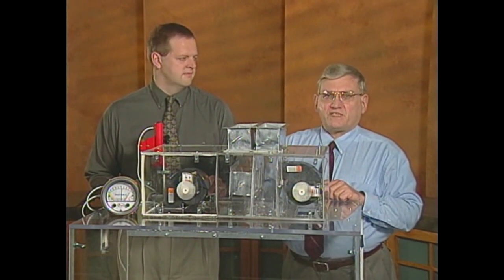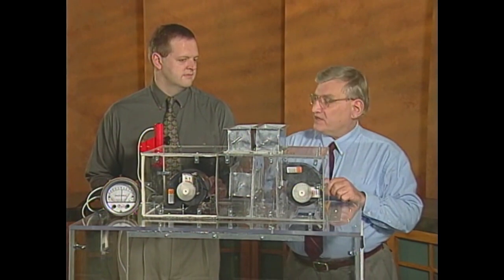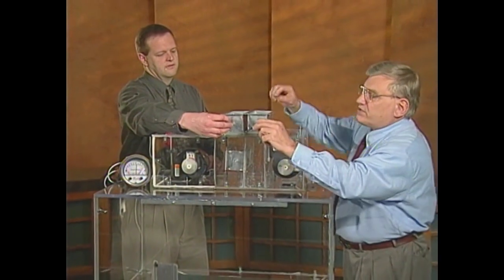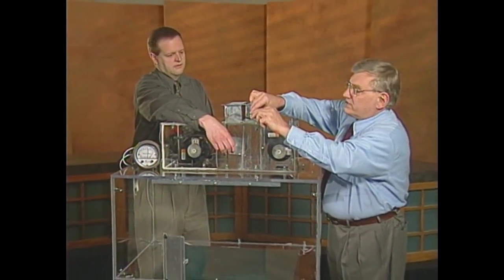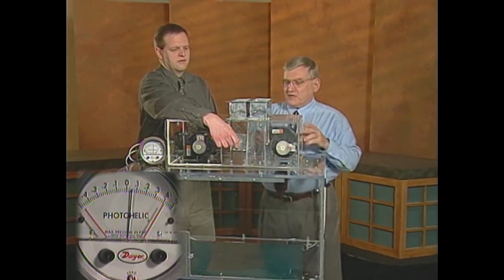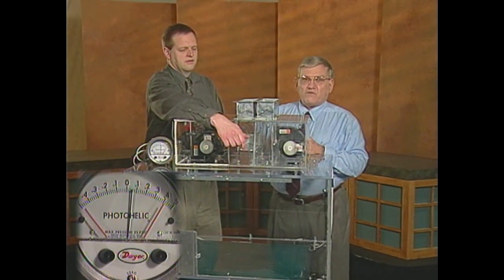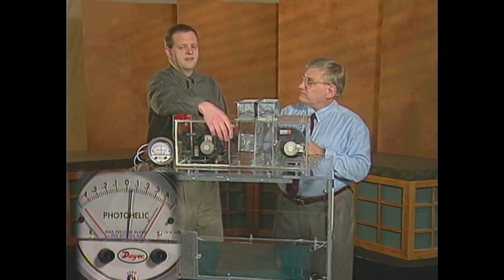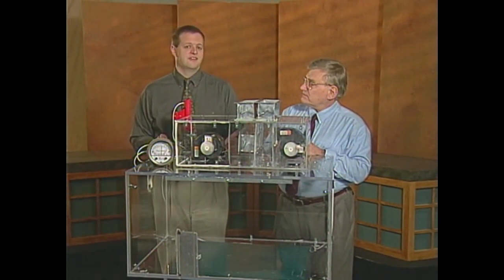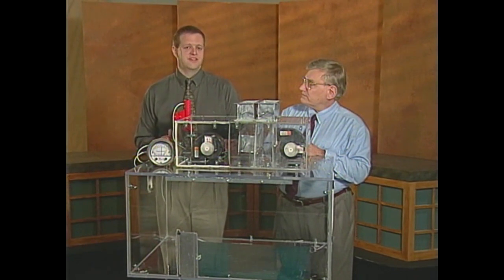In this case, we fixed the outside, return, and relief dampers for the desired building pressure. John, if we open the outdoor air damper and close the return damper and the relief damper all together, we can maintain the building static pressure. This rather simple system is fairly effective on constant volume systems for maintaining space pressure. Yeah, this simple strategy may be adequate for constant volume systems with constant local exhaust. No pressure sensors are required, and the controls are pretty simple.